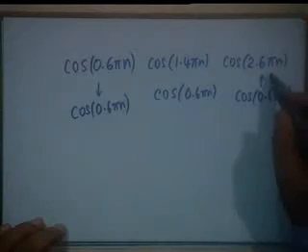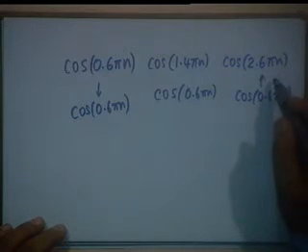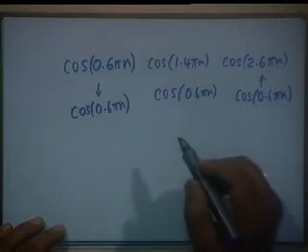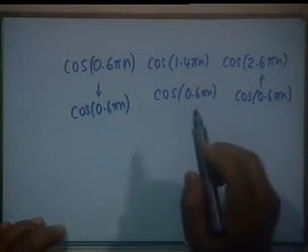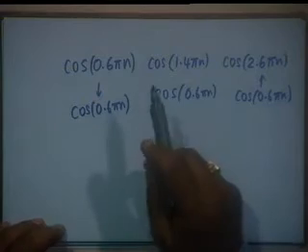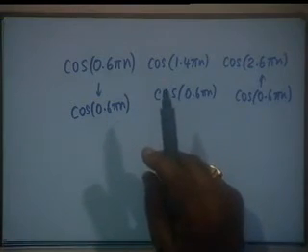Similarly, the 13 Hz signal poses as 3 Hz, and therefore, if the initial signal was a combination of 3, 7 and 13, the signal after digitization or after sampling becomes simply 3 Hz.